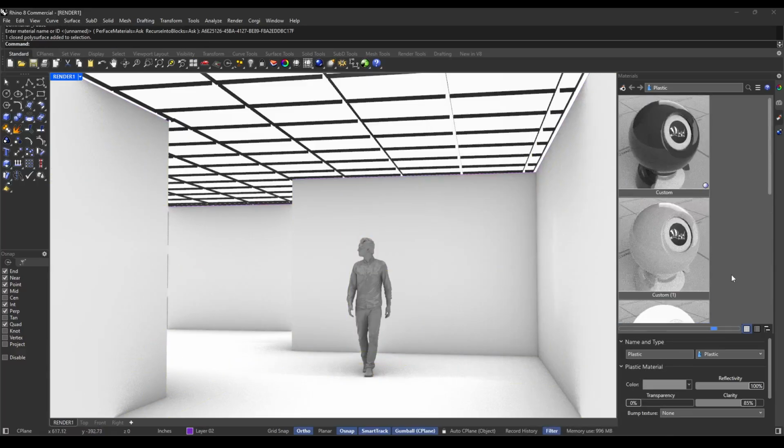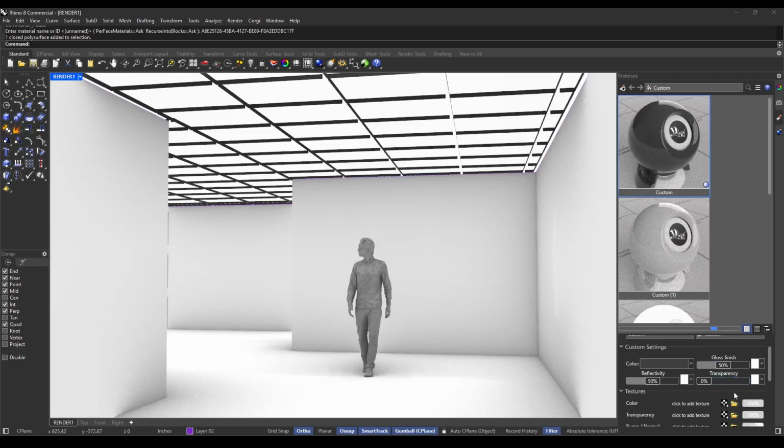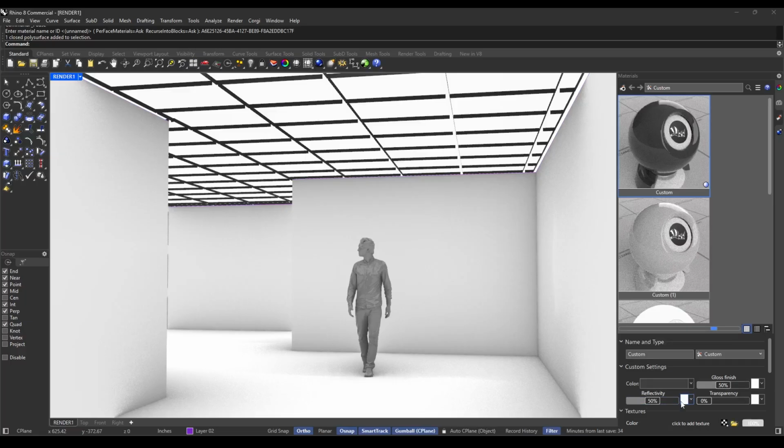Now we'll go back up to the frame, and the frame is too reflective here, so it's actually reflecting the light completely. So if we go here to gloss, reflective, change how reflective it is here. All right, let's take a look now.